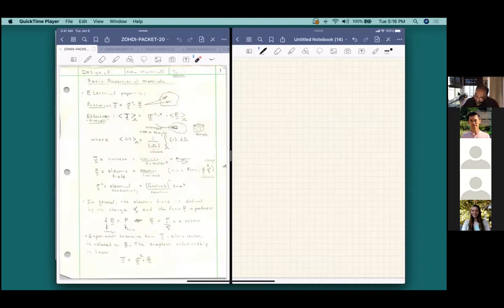Also, in terms of the current field, it's given by, of course, amperes per meter squared. That's why it's not simply just I, as it usually is in your undergraduate studies. This is the amperes per unit area. Then you have the electric field, which of course is nothing more than the newtons per charge or coulomb. And then the conductivity, which is given by a variety of different things to balance out what is on the left-hand side and the right-hand side.